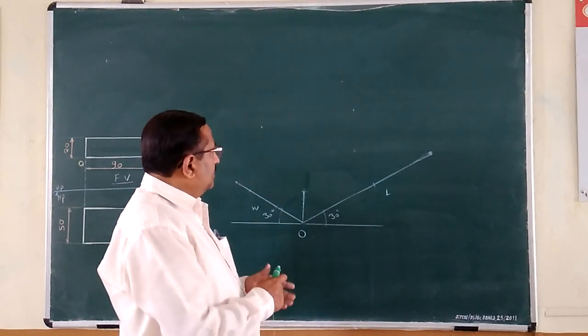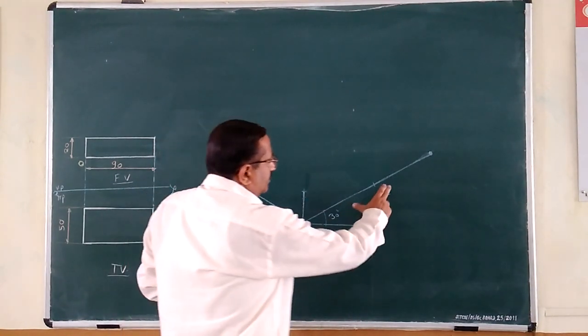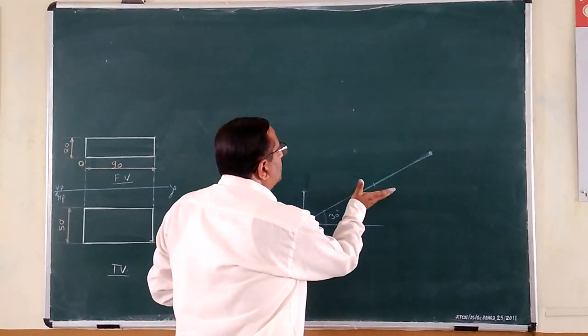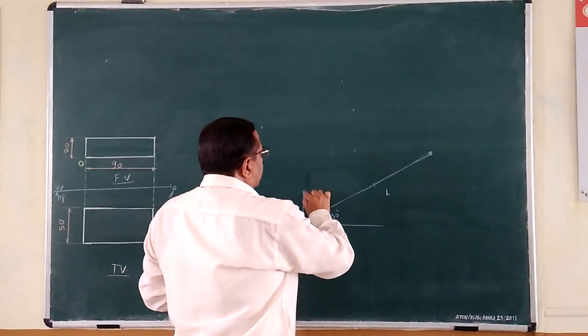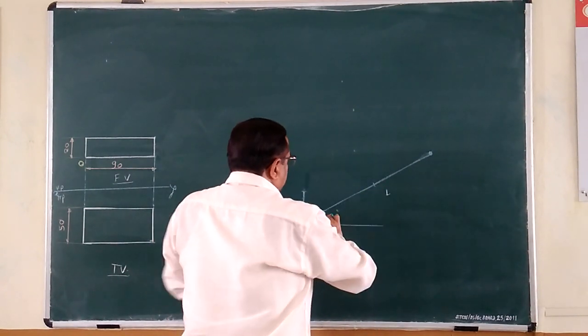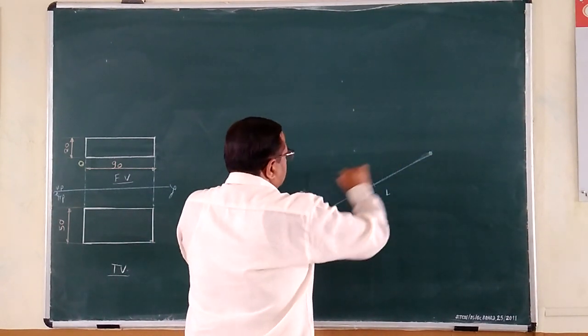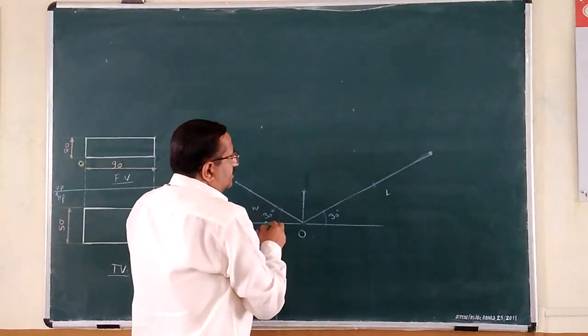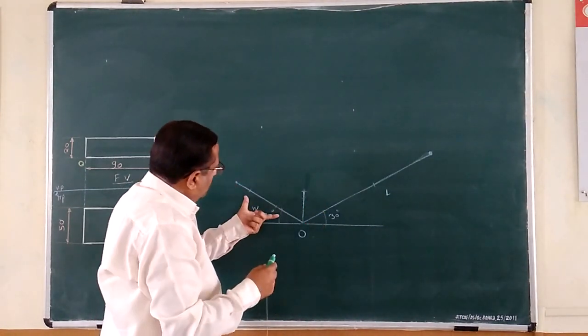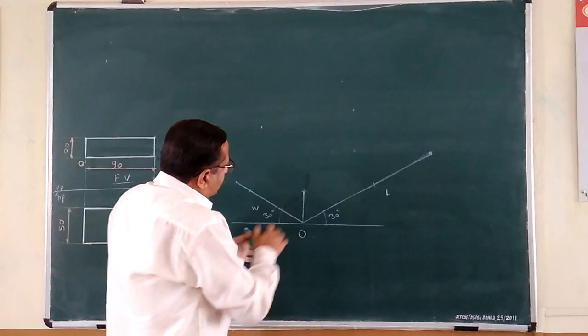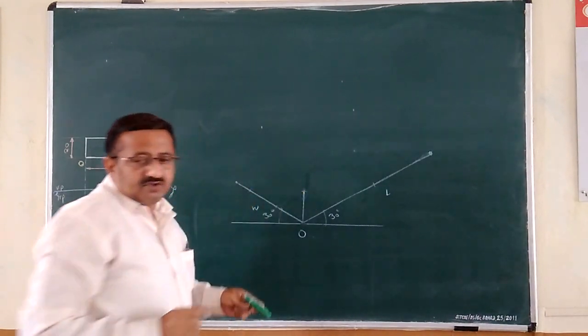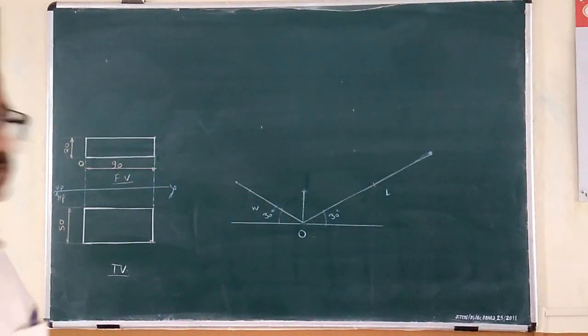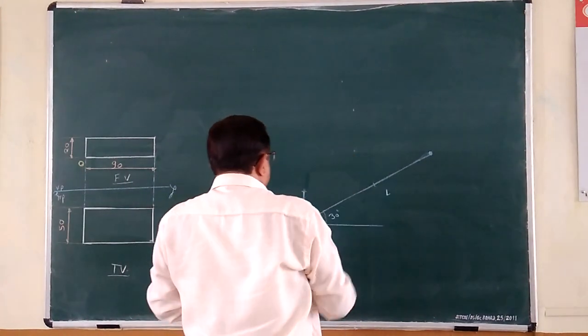What do you have to do? Just hold the blade of the roll and draw here, make it roll in this way in the upward direction, and get the right 30 line parallel to this baseline through this tube. Similarly, on the left side also, roll it here in this way and get the left 30 line through these tubes. So I will start initially by drawing those parallels.